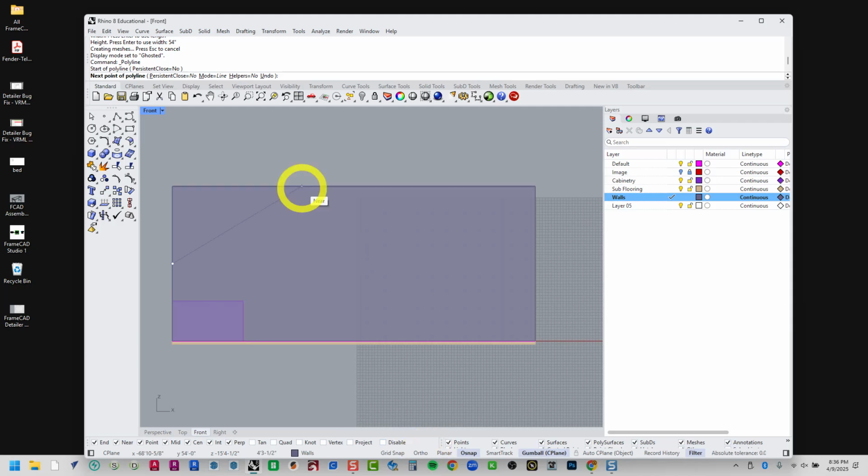Okay, so now let's go to our perspective view. I'm going to delete this box that I've drawn, and what you see is you'll be left over with this new shape that you've drawn. I must advise you, if you utilize any object snapping and any 3D objects while you are making a 2D object like a polyline, be super careful.